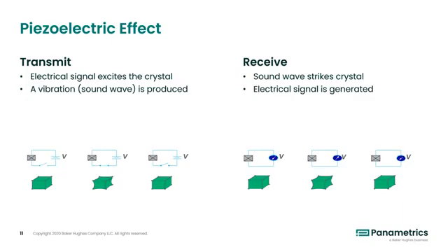On the receiving end, the receiving transducer is listening, so that circuit is closed and completely listening until that sound wave strikes the crystal, causing it to vibrate, and then that vibration is turned into electrical energy to be returned to the meter electronics.